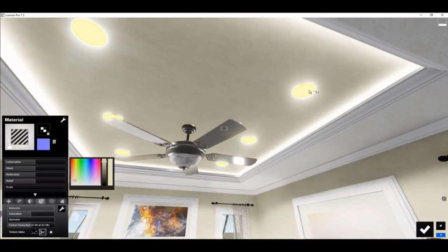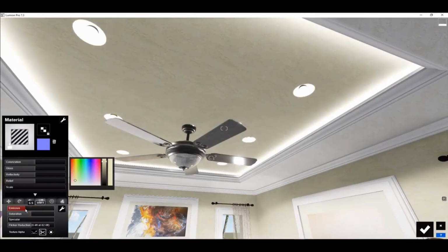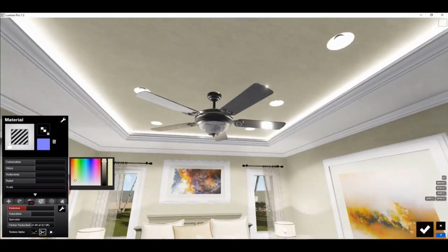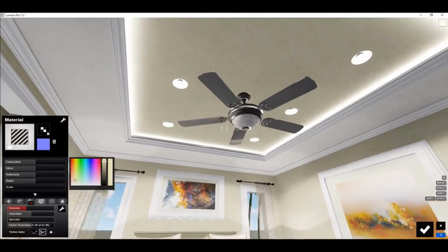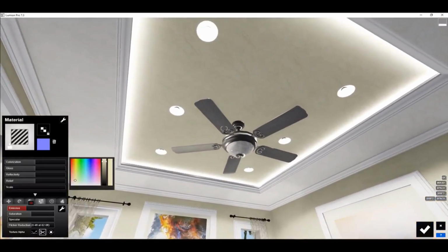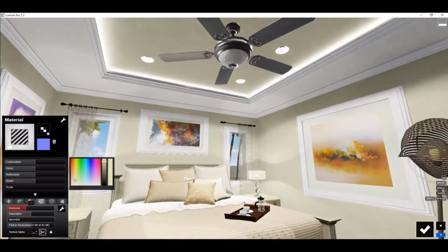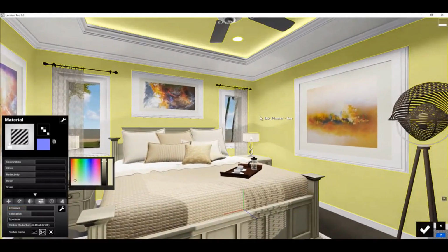But let's make sure that we don't go nuts on that emissive material. It seems like for our can lights, we can still keep that emissiveness down to about 10. So I'll just double click on that slider and give it a precise value of 10. The nice thing about those emissive materials is we can really dial those up with our effects. So that's why it's important to not go overboard on the lighting brightness settings, because then you have more control with your effects.